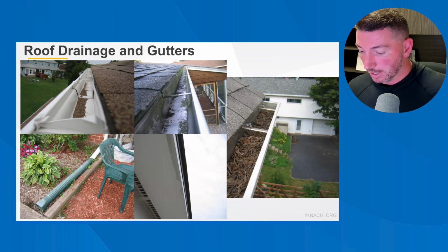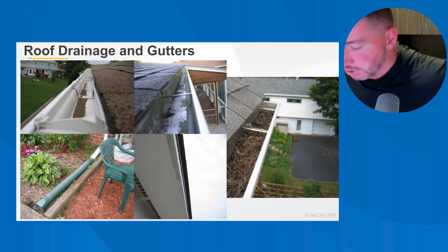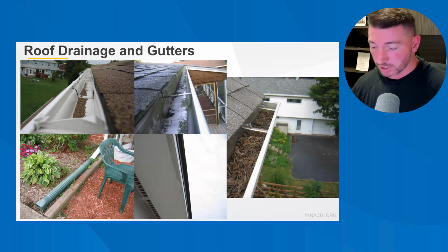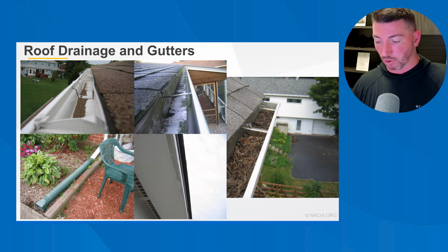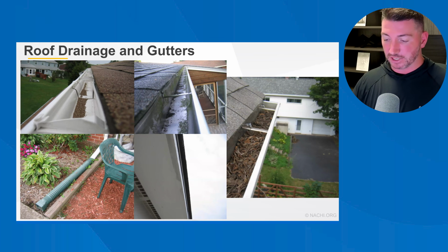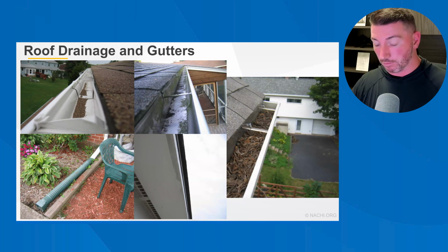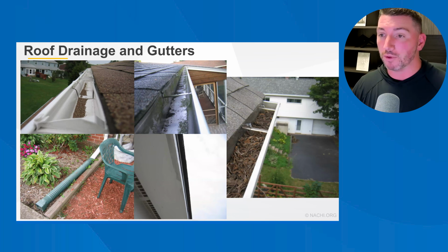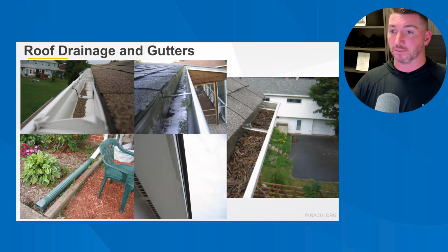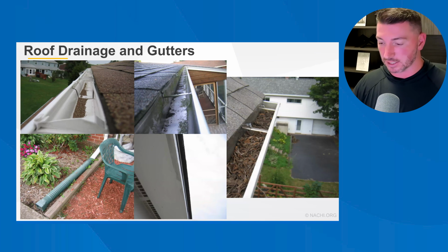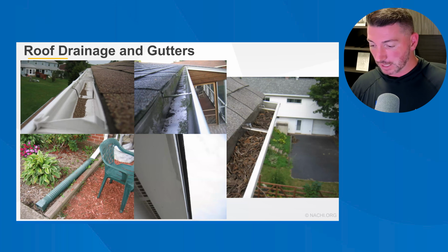In terms of standards, home inspectors are not required to measure the amount of gutter slope. To do it accurately would be time consuming. It would require a transit or water level. It would exceed InterNACHI standards of practice. So if you think that it doesn't look sloped correctly, one big indicator would be whether or not there's any standing water in a gutter that does not have a clogged downspout. But without a scope, you'd have a tough time knowing whether or not a downspout was clogged if it's not visually accessible at the time of your inspection.